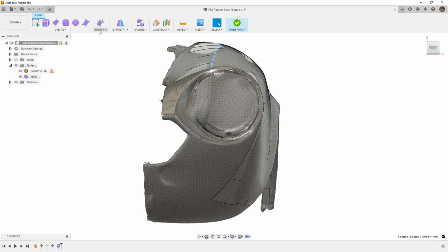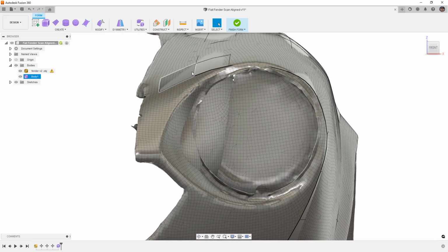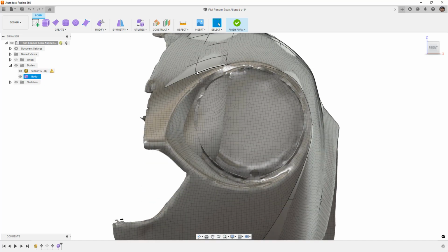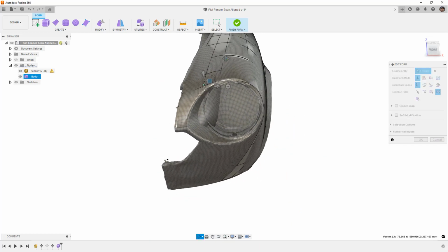I'm going to just try to add one now. I'm going to go to Insert Edge. I'm going to put it right in the middle, but I'm going to use Exact. And when we use Exact, it's going to keep the exact same shape, which means that all the stuff that we did back here on the broad part of the fender where we didn't have a lot of curvature is going to stay, and all the stuff up front is going to stay, but this is the area that we need to adjust. So I'm going to take that vertex and pull it down a little bit. Probably going to take this vertex here and pull it down and get a pretty good result there.